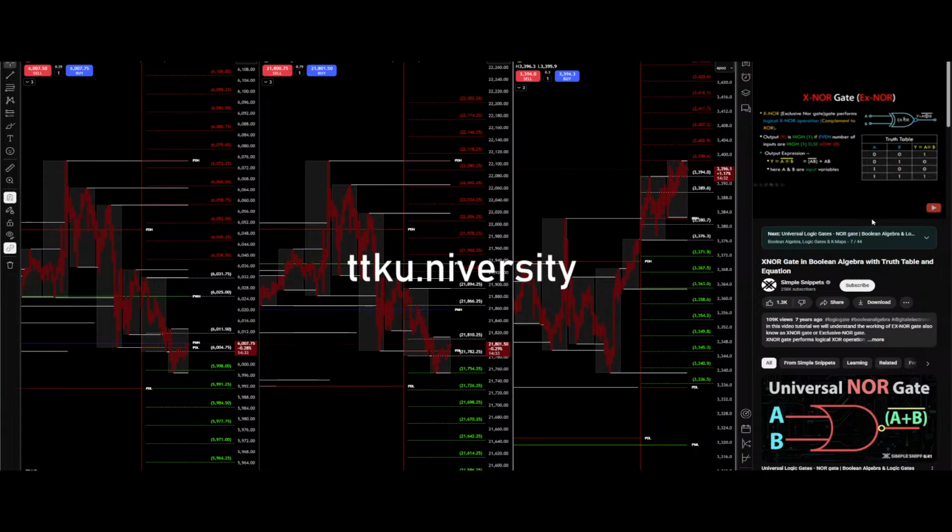So this is an XNOR gate, and if I go to the previous slide, here you can see the XOR gate did not have this bubble, but our XNOR gate has this bubble. So that is the only difference in the symbol, and the output is exactly opposite, or complement, to the XOR gate. Let me read the output case written in English over here. Output Y is high, that is, Y is 1, if an even number of inputs are high, else it is low. This is exactly opposite to the XOR gate, where the output is high if an odd number of inputs are high, otherwise it is low.